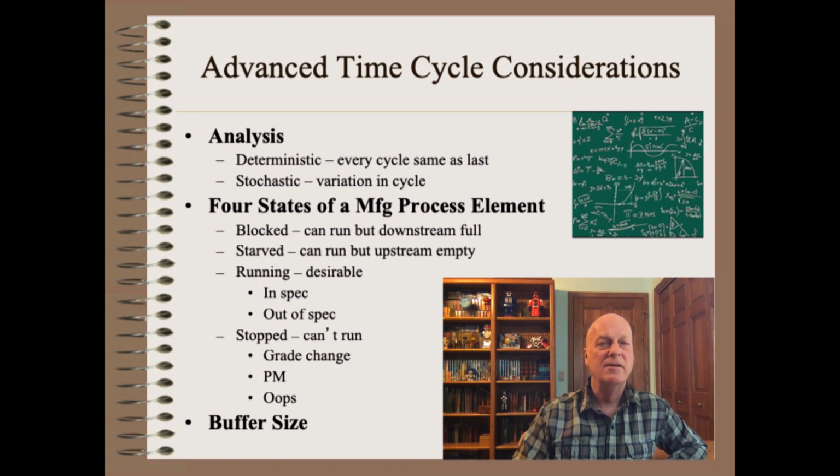In the paper industry, the buffer between the paper machine and the finishing ReWinder may be 5 to 10 master rolls. Here, upsets at the finishing winder or downstream could last for a few hours without shutting down the paper machine. The biggest buffer I've personally seen is one board paper machine which had 150 master rolls in storage.